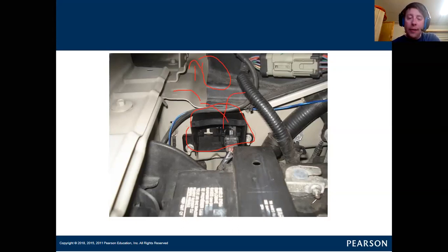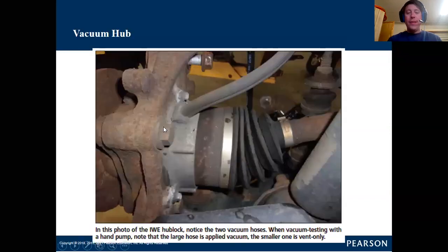With a little bit of age, those vacuum lines become compromised, and even the vacuum switch becomes compromised, and water, saying that very, very precisely, water is able to dribble by gravity down here. And the water gets in that hub and it rots it. It causes rust.